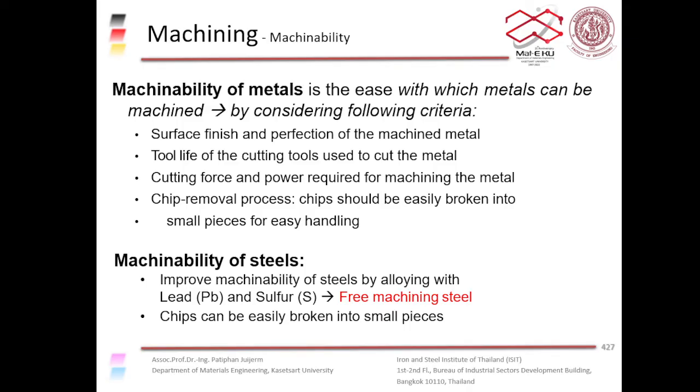For example, if you are producing a component and choosing a material for that component, then you have to choose the manufacturing process that is appropriate for that material. And you have to think about all the economics of producing that component, like what is the cost per unit, so that you choose the correct manufacturing process. It depends on how many pieces you want to produce, and so on.